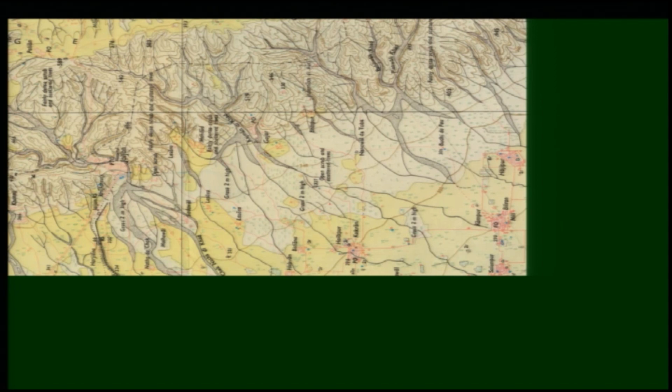Since these are the widely spaced contours and these are closely spaced contours, this clearly indicates that in this area the elevation change is very rapid, in the sense that it happens over a very short distance. Whereas here the elevation changes over a very wide area. So, with 340 here and 380 here, the elevation is changing very gradually, whereas here it is changing very suddenly, because of the closely spaced contours. So, this marks the mountain front, whereas this marks the flat